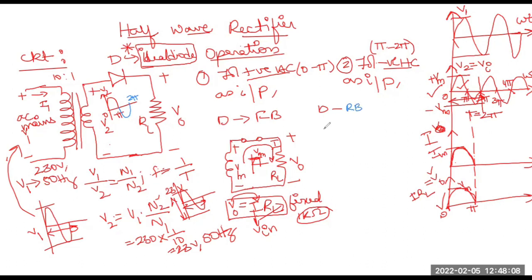So when diode is reverse bias, what is the equivalent circuit? Open circuit, ma'am. Yes, so there is no closed path here. It is an open circuit. Now what about the polarities of voltages here? Negative voltage, so minus, plus, and I show here the maximum case. Even though your input is changing, starting from 0, slowly going to negative voltage and then coming back to 0, for our easy understanding we take the maximum case. So this is minus Vm. Minus, plus.